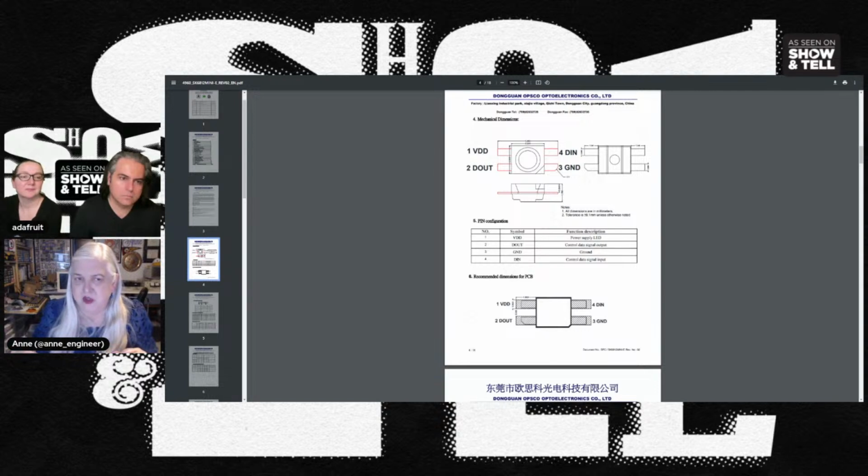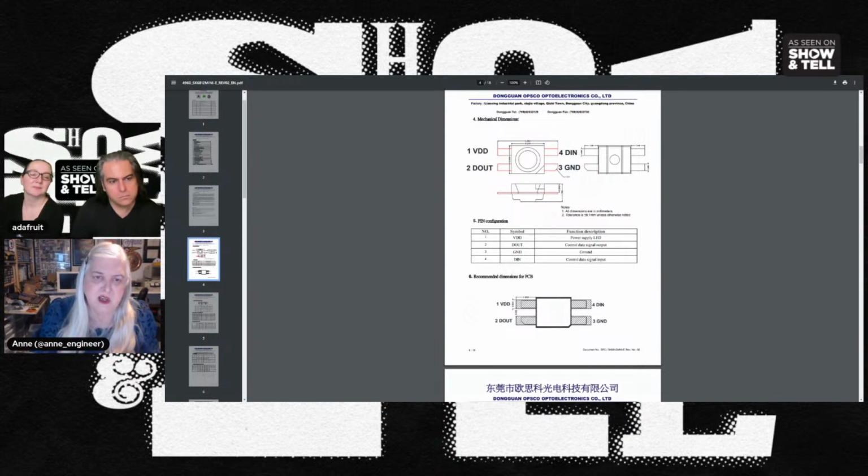And here's the data sheet. The footprint was okay. What I did was I added a cutout so it could be reverse mounted. It wasn't there, so I modified the footprint to automatically do that. So it put the 3 holes here all nice and neat, and the board manufacturer likes them.